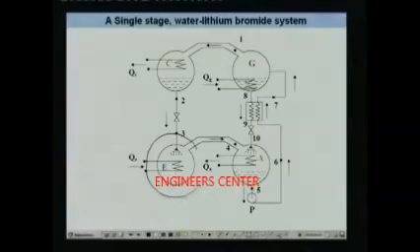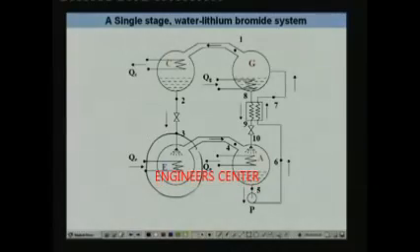Okay. I will just give an example. For example, if you are taking, let us say, the evaporator. If you are applying mass balance to the evaporator, what is the mass balance? Remember that here the cooling water, chilled water and all don't come into the picture, because we are not really considering how we are supplying heat or how we are rejecting heat. So for our analysis we are concentrating only on the refrigerant side, that means inside the system.